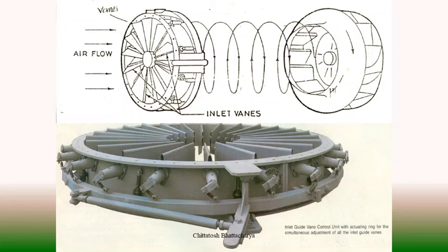So inlet guide vanes are basically a better arrangement compared to suction dampers in suction ducts, and they are better in terms of controlling within the regime, as I told, from 25 to 70% of the opening, when we get 100% to 30% control over the total flow.